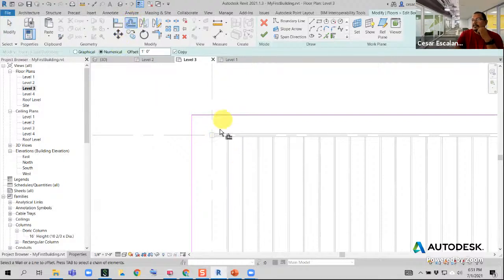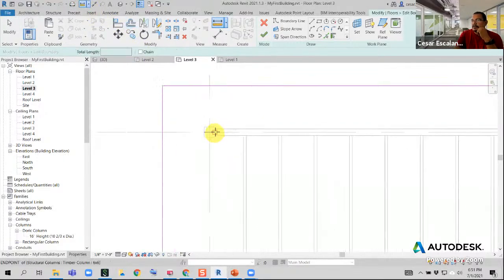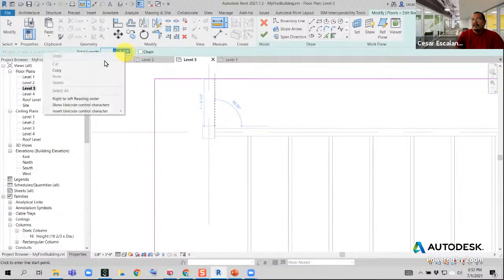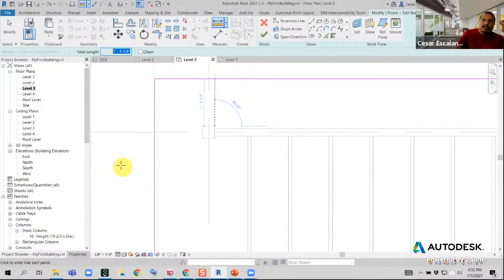And we need to interrogate the distance of the offset. And so that distance is going to be, you can measure elements using this measure tool. A measure, you can call it a transparent command, because you can use it in the middle of any command. If you need to get an idea of a measurement in the middle of a command, you can invoke the measure tool, and this is 1 9.25. And in fact, this is the total length here. You can drag it from the cell. You can right click and copy, and that way you don't have to type it.